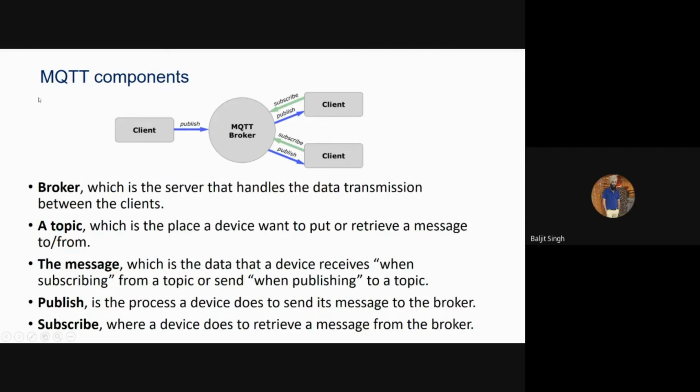Let us say here one sensor node is having one microcontroller and all those three sensors: temperature, this BME, and the soil moisture sensor. Another microcontroller with again those three sensors. Again another microcontroller with three sensors. All the microcontrollers are having LoRa module and they are transmitting to this server, this gateway. So this client is that gateway which then gets connected to the server and it publishes on MQTT broker. Broker we will discuss just in a few minutes.